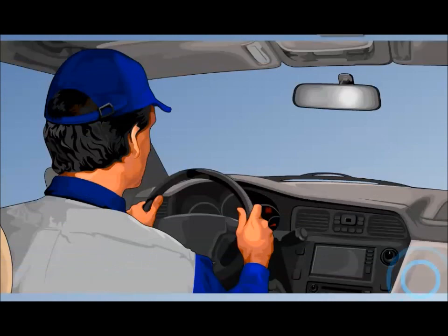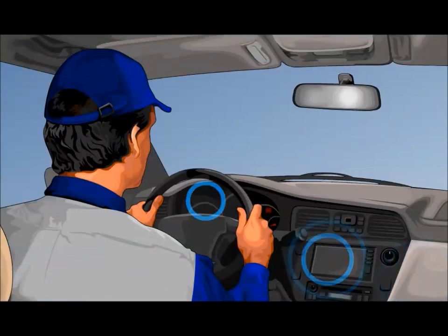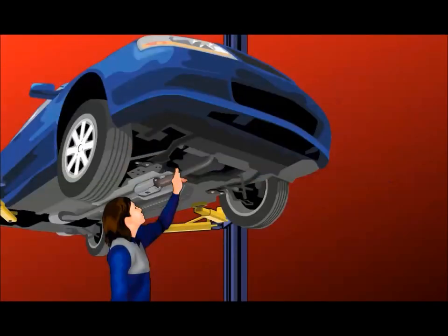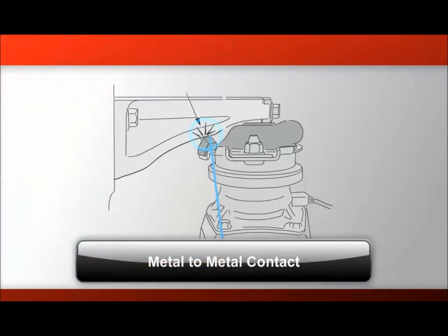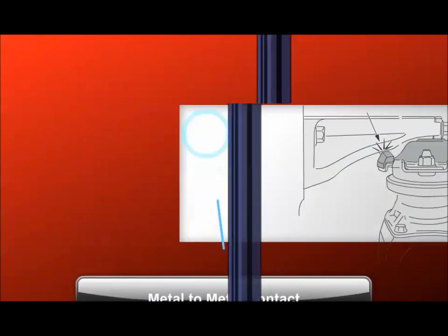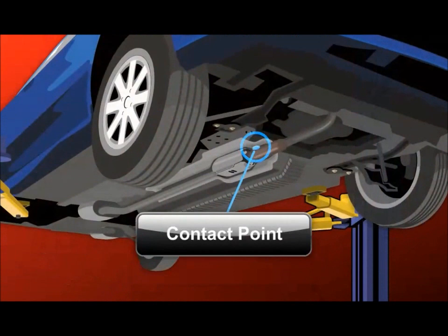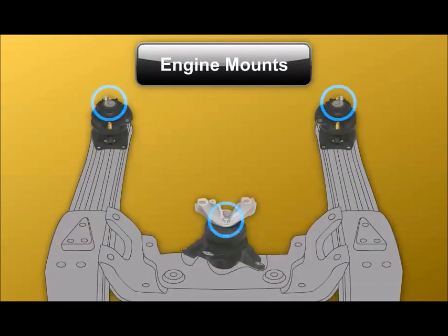If symptoms point to a vibration transfer issue, visually check for evidence of vibration transfer. Make sure the engine mounts are aligned and check for scuffed paint or polished metal where driveline components could rub against the vehicle body. Engine mounts can create vibration transfer through several faults.